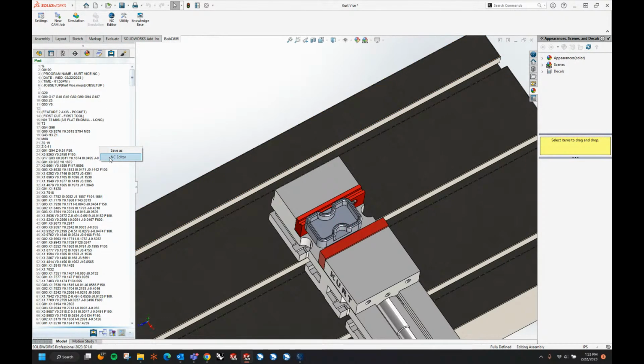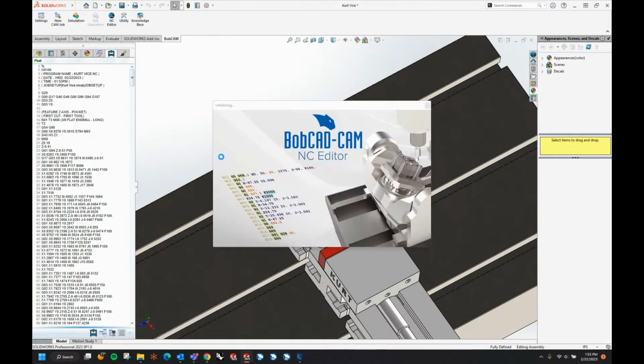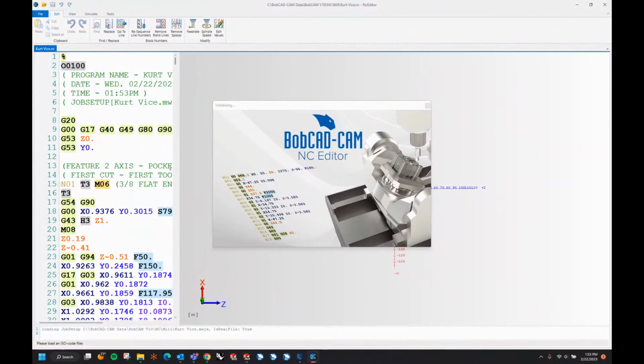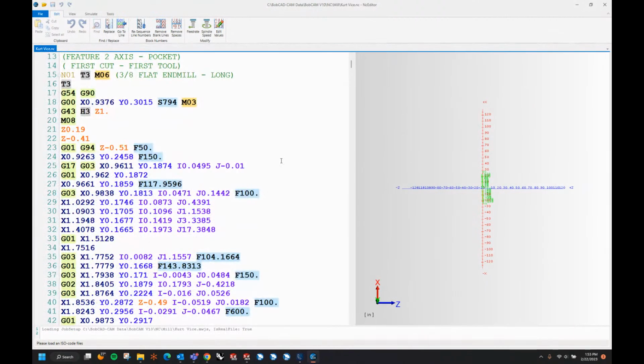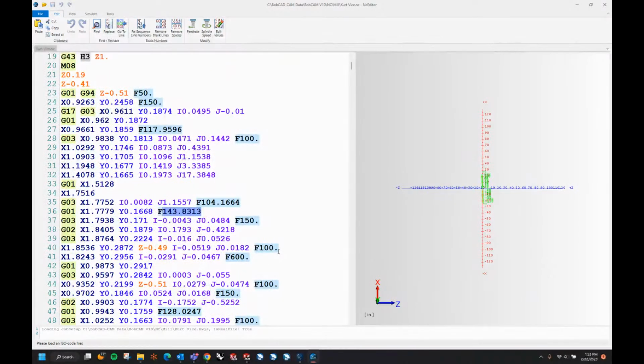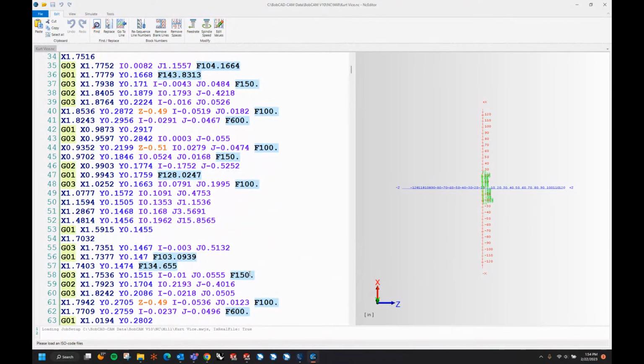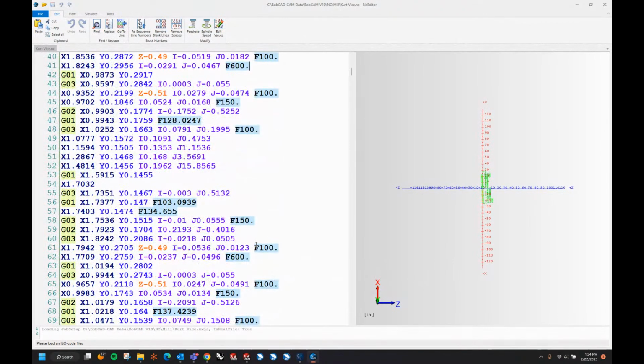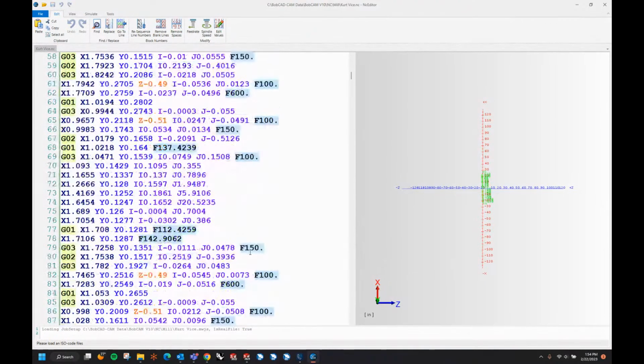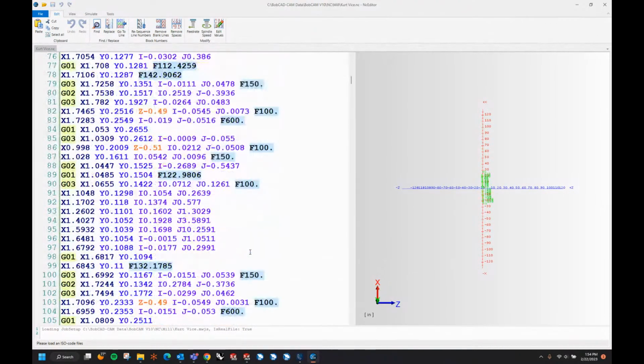this one should, but it may not either because there's really not a lot of variation in those corners. Yeah, you can see it's sped up a little bit in some of those corners because it's a lesser volume than the step over that we've defined. And it looks like my default machine has 600 inches a minute for the linking. 128, 103, and you could see where it's ramping up and going back down because of the volume that it's engaged with.